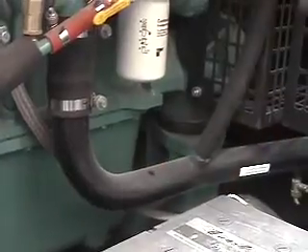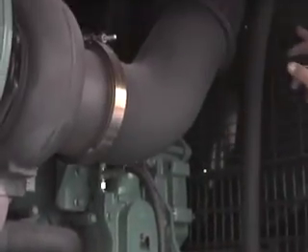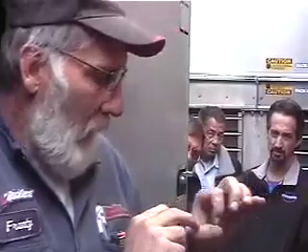Like I said, the black tube is coolant for the radiator. You got the other black tube that's up here that's also coolant. Unless you get way back there or stand up on top of the tank on top of the radiator, there's a little sight glass. It's about 3/4 of an inch, the glass itself. It has coolant in it. You want the coolant to be about in the middle of the glass. If you fill it all the way to the top of the glass, next week it's going to be back down, because it's going to push it all out when it heats up and shoots it out the bottom. So you always want it down about the middle of the glass.